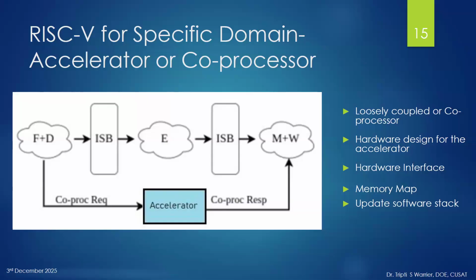If there is configuration that you have to do, you will treat it like how you operate a peripheral, with configuration registers, and then the start and end, all the sequence of control that is required for completion of the task. That handshake has to happen. So generally that happens using memory maps, and that has to be taken care of.